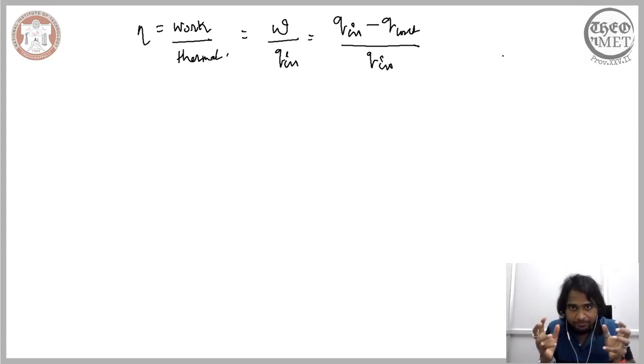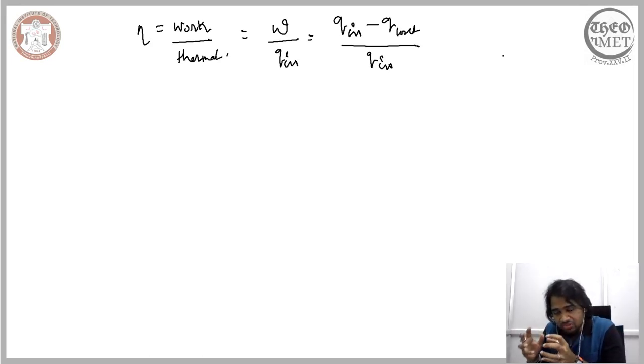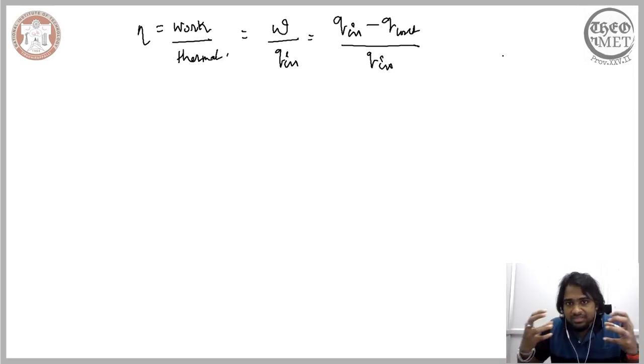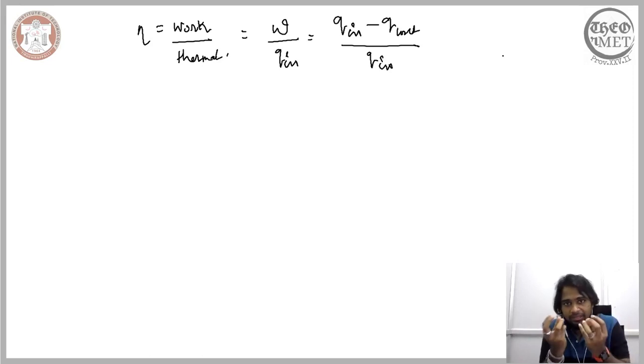One other fundamental concept that helps us relate the work done to the heat transfer is that, since we are able to quantify the heat that is lost during the operation of the heat engine, there is not much change in the internal energy. This constant internal energy allows us to relate the work directly to the heat transfer involved, which in the operation of a heat engine is the difference between the heat input and the heat output.